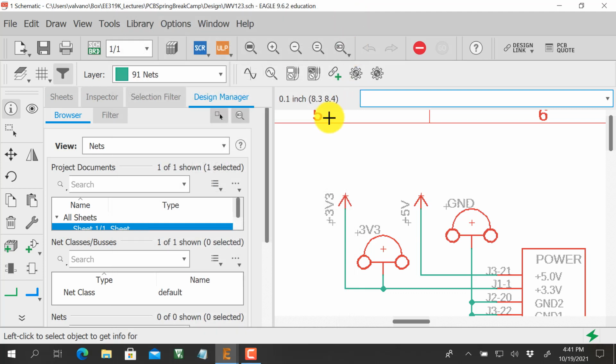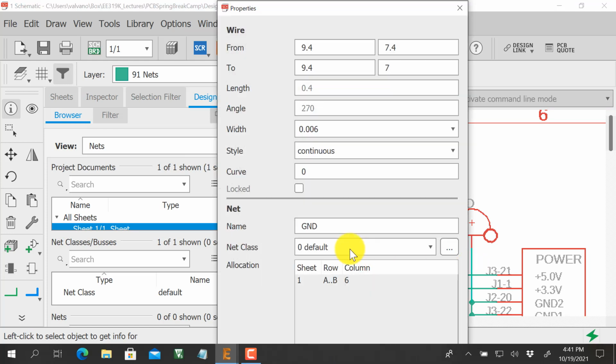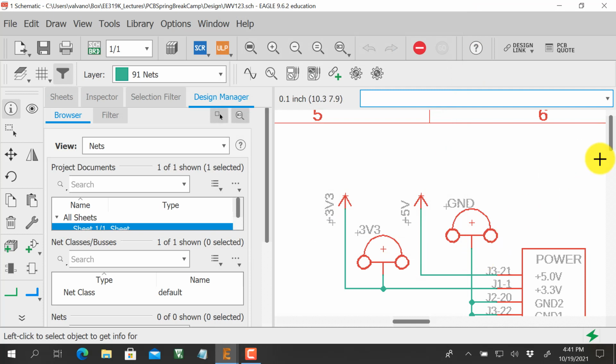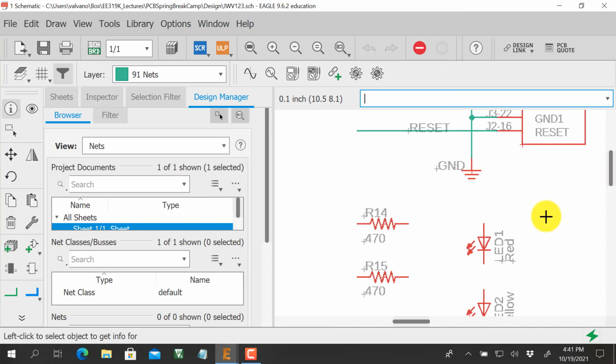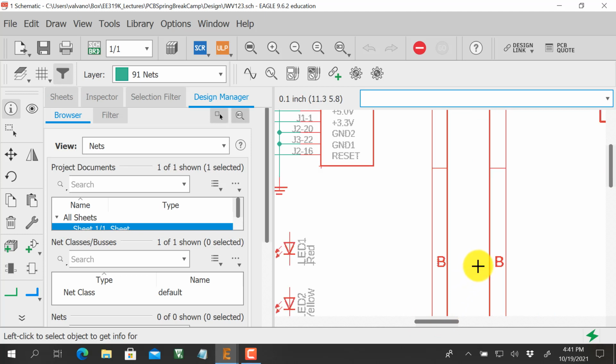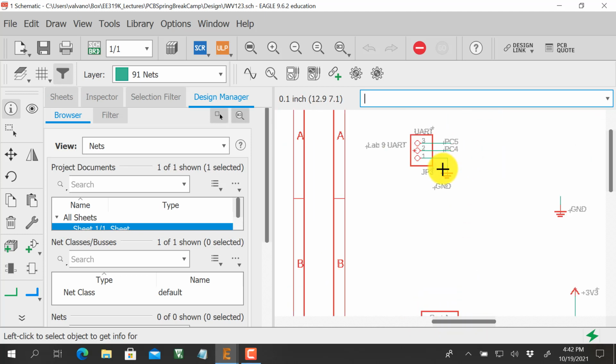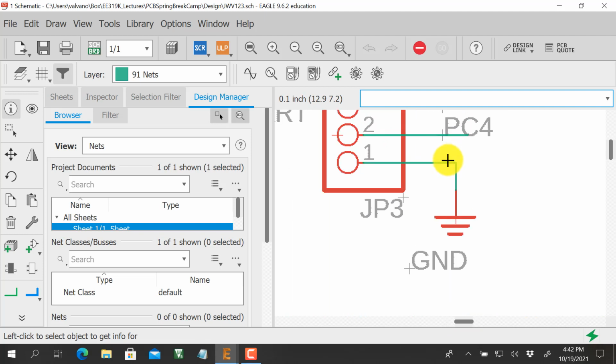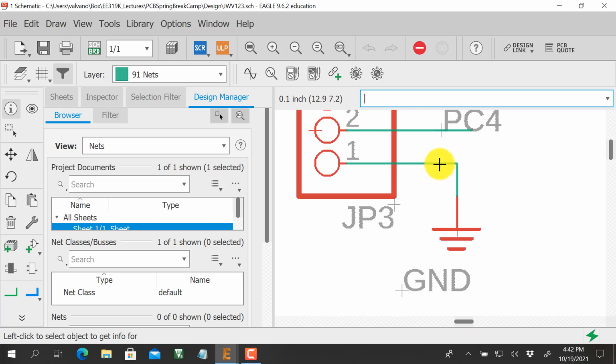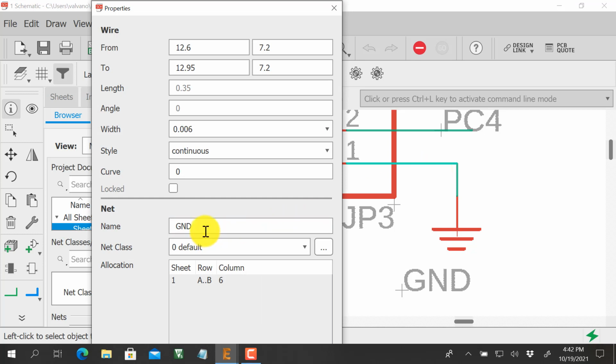So the next thing I want to observe is the nets. Again, the green lines are the nets. For instance, if I click, again, I'm doing an info, I do the command first, and then if I click on a net, it'll tell me what net it is. It's a ground net. You notice that was ground. Down here, or over here, wherever I saw it, I saw another one. Here's another one. Zoom in here. So that's a control roll bar. Here's another line. It's also ground, GND.